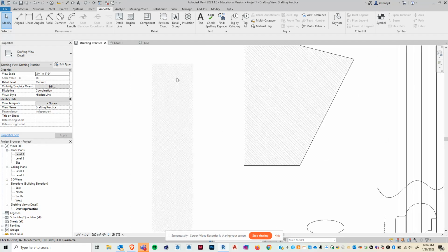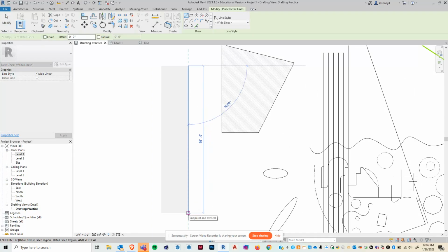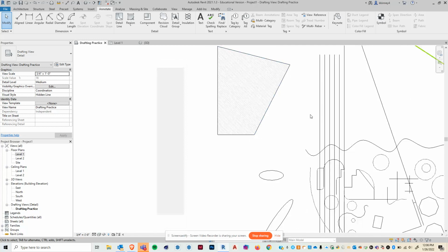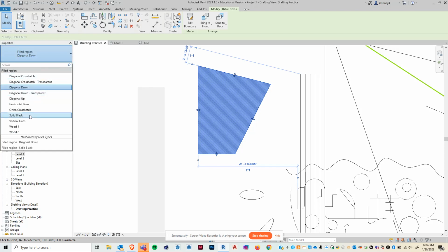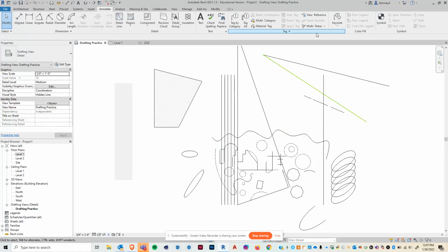Now this hatch is pretty small because this drawing I've made is actually quite large. If I just drew a line here, I can see that this is 30 feet long. So that's why this hatch is pretty tiny. Okay, so we can go here, select different hatches. And if you wanted to make your own hatch or you're not seeing something on this list, you can corner me in class and we'll go over that. So I'm going to leave it here. Main takeaway: drafting tools, modification tools, how to create your own line weights, and how to create a filled region, otherwise known as a hatch.